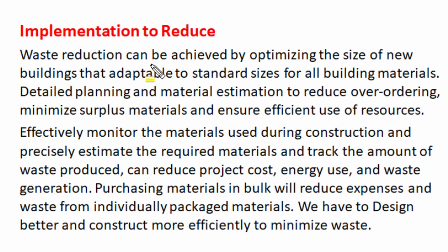The first step of waste management is implementation to reduce wastage. Construction and demolition waste reduction can be achieved by optimizing the size of any new construction project so that it adapts to standard sizes of building material. We know tiles are available in 8-inch, 12-inch, 16-inch, and 24-inch sizes. Larger slabs, boards, and metal sheets are available in sizes of 4 feet to 8 feet. If the dimensions of a building component are designed as per those standard sizes, then we can reduce wastage.